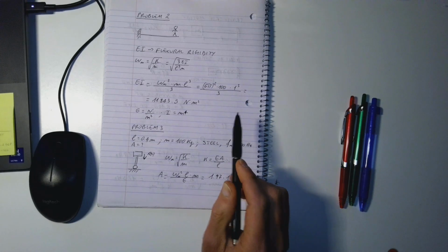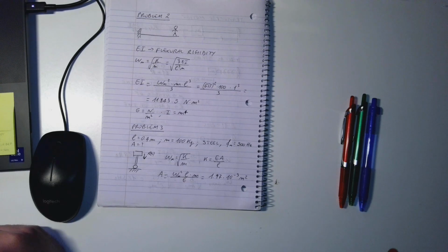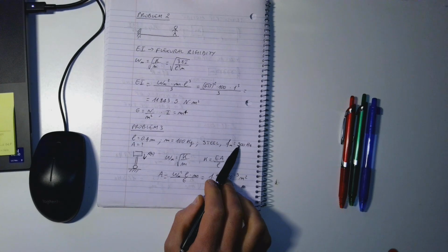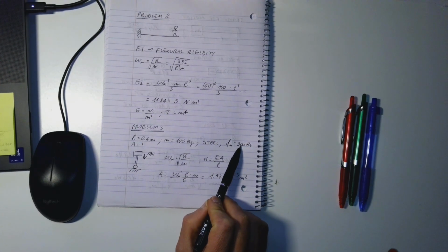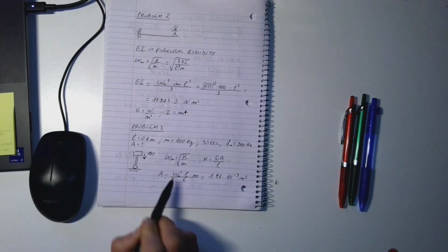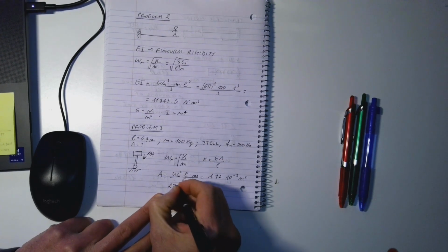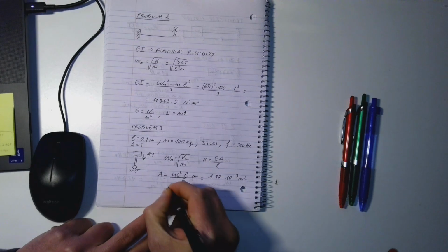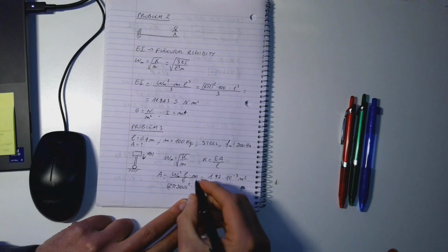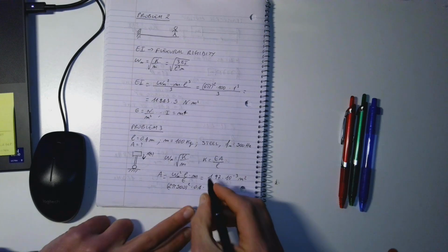Also, please pay attention to what you put here, because omega n is the natural frequency expressed in radians per second. Here we have the natural frequency expressed in hertz, which means that we have to multiply this quantity by 2 pi in order to obtain omega n. So the numbers that we put here are 2 pi times 500 squared, L is given already in meters, so times 0.4. The mass is already given in kilograms, so times 100.